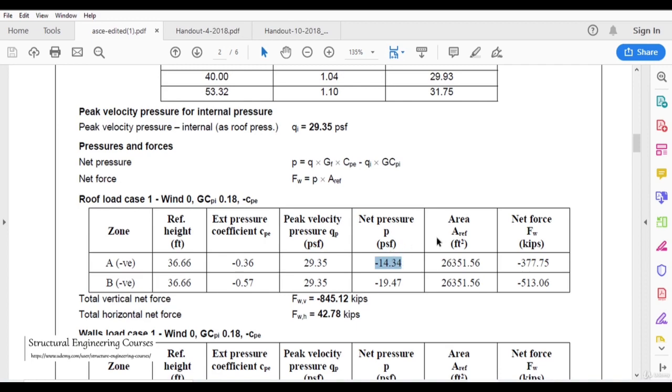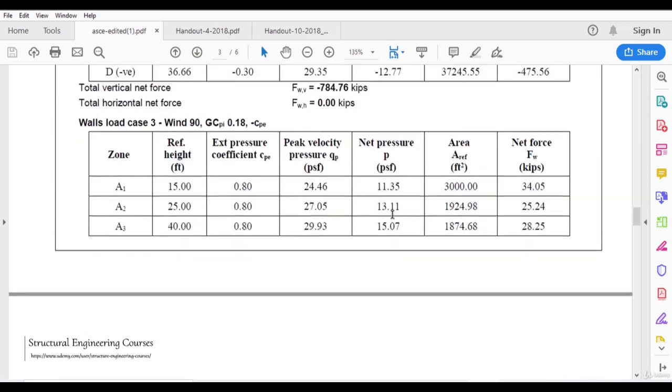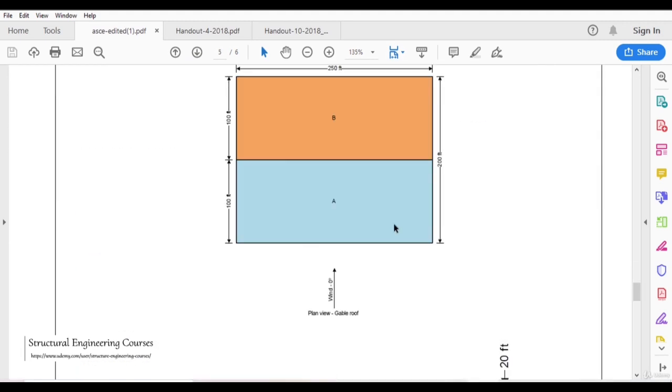That dimension needs to be perpendicular to the face on which we are applying that loading. So if we are talking about, let us say this area here, suppose there are 10 portals with this 25 feet spacing. So for each and every portal that we are talking about, there shall be 12.5 feet on the left effective area and 12.5 feet on the right. So the total effective area of that portal shall be 25 feet.